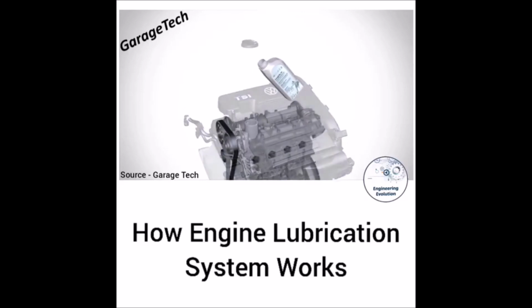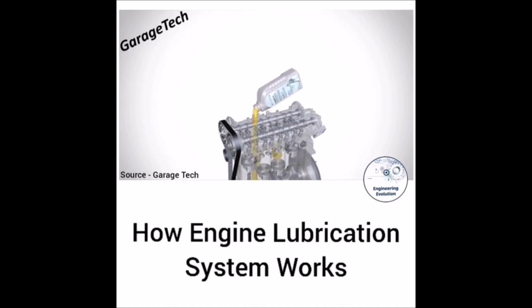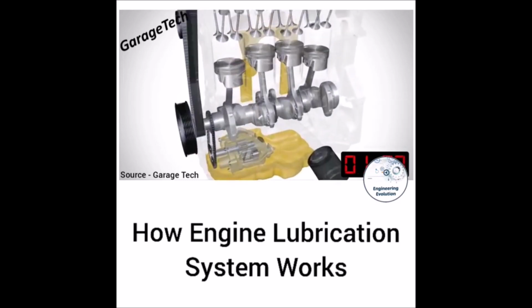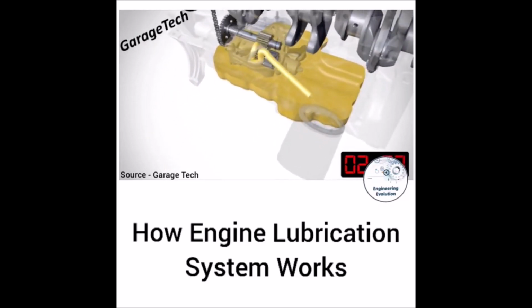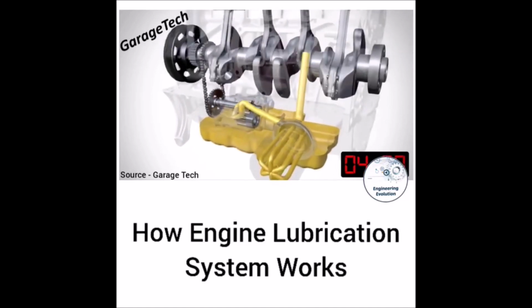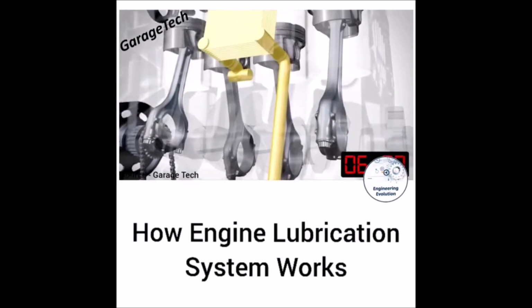And we're just going to fill it back up with oil. So you fill it back up at the top through the oil filler neck. The oil then drains down into the bottom of the engine, into what's called the sump. Now when we start the engine, the rotational movement of the crankshaft, etc., will start to turn the oil pump, which draws oil up from the sump and then into the oil filter to filter out the oil. It then goes up to the oil cooler. So the cooler is there to cool the oil down once the engine gets hot.